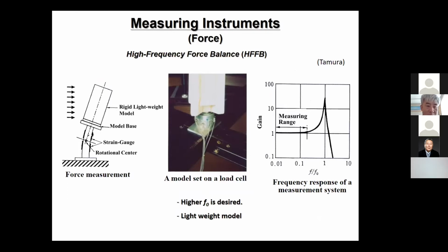And here is a high frequency force balance test. You can find that we can use load cells to measure the wind force on the structures. But here people have to attend to the frequency response of all the facility. For this kind of high frequency force balance, a higher natural frequency is desired. So we have to use very lightweight models for the force balance measurement.